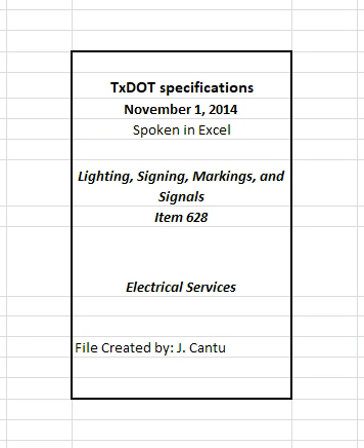3.1 Installation. Furnish and install electrical service equipment. Ensure components of the electrical service meet the requirements of the electrical detail standards. Follow NEC and local utility company requirements when installing the electrical equipment. Coordinate the utility company's work for providing service.